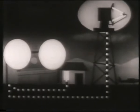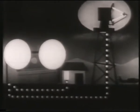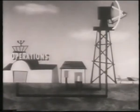The reflected energy in the form of weaker pulses is carried from the antenna into the sensitive radio receiver, where the pulses are amplified and passed into a cathode ray tube, in which the radio energy bombards a fluorescent coating inside the tube, or scope as it is called, and leaves a visual glowing area of the object struck by the transmitted pulses. The whole process of generating pulses, transmitting them from the antenna, receiving the echo from an object, and producing an echo on the scope takes only a minute fraction of a second.